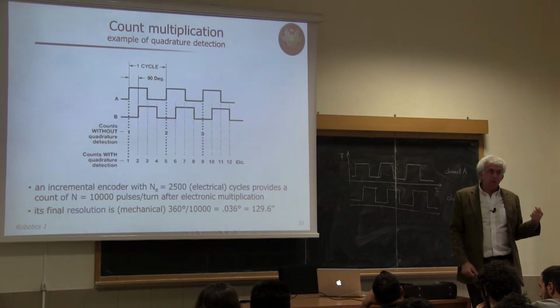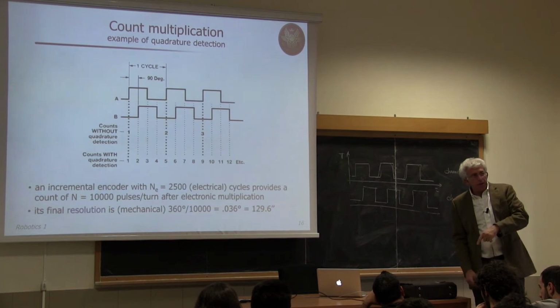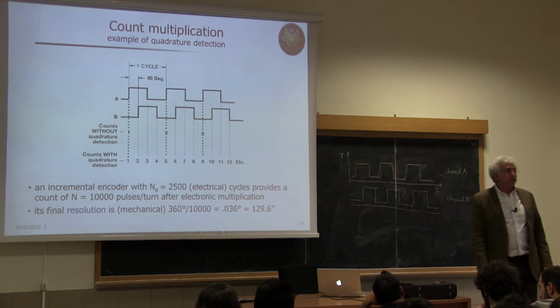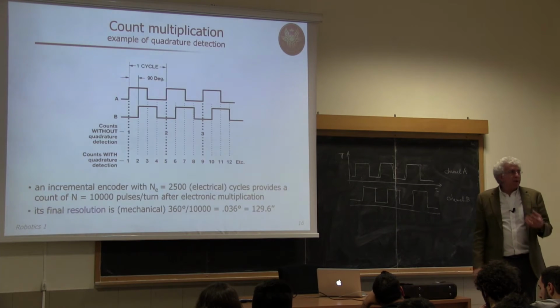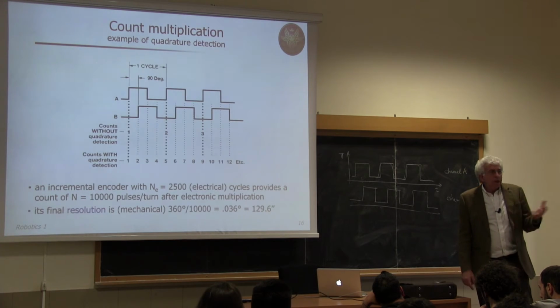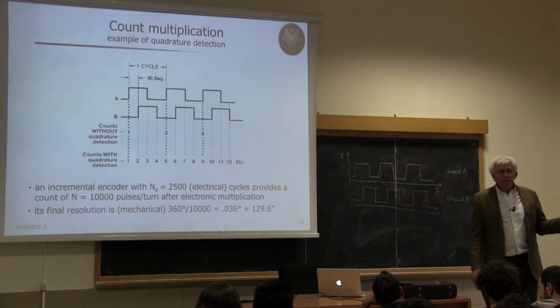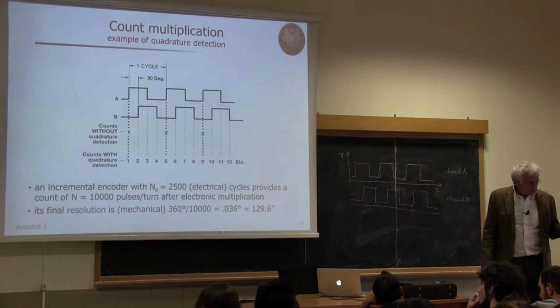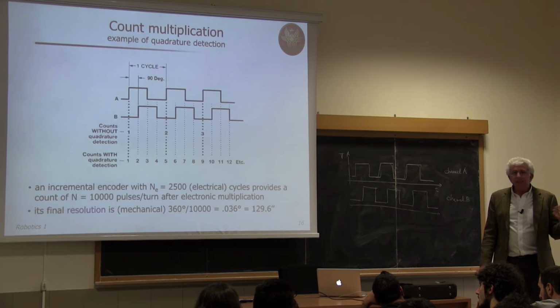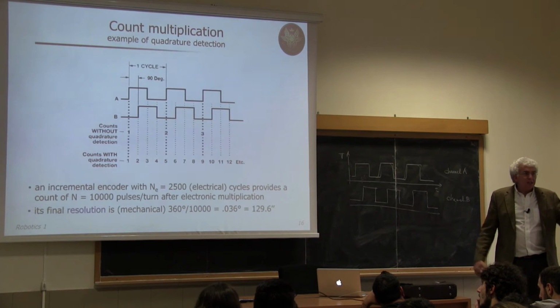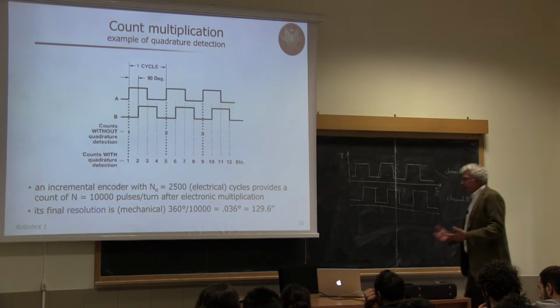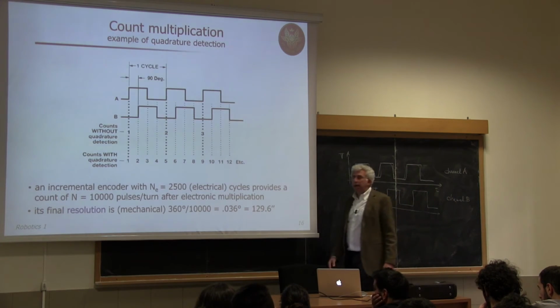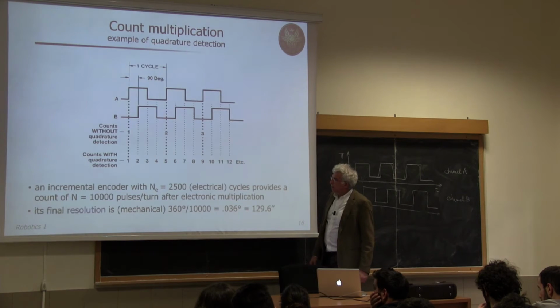If we mount it on the motor side, we will be more accurate in measuring the link position. But if we have some elastic effects, we will lose this because we are measuring before the transmission. So any elasticity in the transmission is out of the measurement loop. Okay? So there is a trade-off between these 2 aspects.